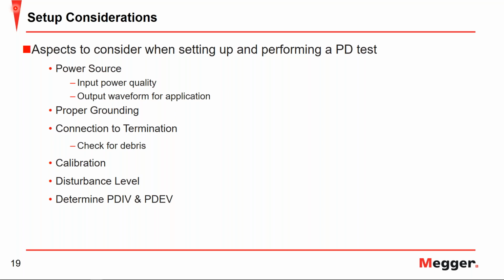And then of course, the worst case scenario is both your inception voltage and extinction voltage being below operating, which means you have partial discharge taking place all the time while that cable's in service. So just three examples of why finding these values is so important.